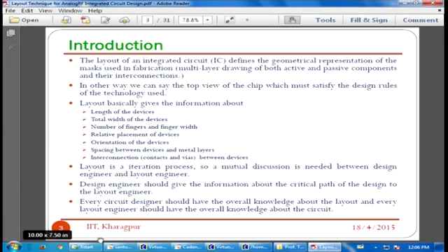So generally we are using metal 9 and metal 8 for power routing, and metals 5, 6 for signal routing, and for control lines generally metal 2, metal 3, like that. Also for biasing purposes we are using metal 2, metal 3, but we are using proper shielding, otherwise it will create some problem, because for CML design, biasing is very important. If any noise enters the biasing path, then it will create a problem.